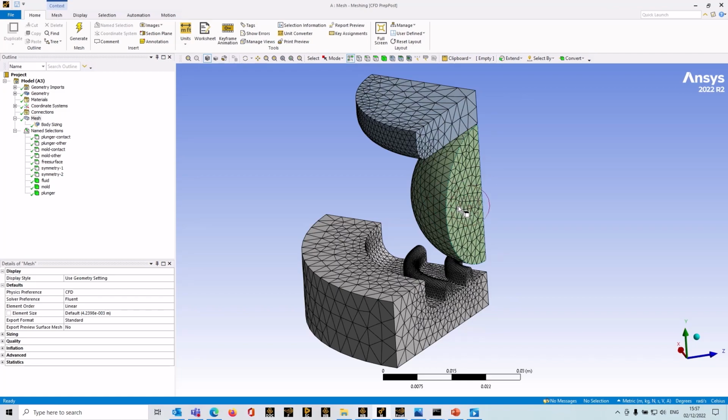The reason for that is that it's very difficult to anticipate where to refine the fluid in one of these simulations. So we're actually going to be using solver adaptive meshing. So that's why we've started with relatively coarse mesh on the fluid itself.